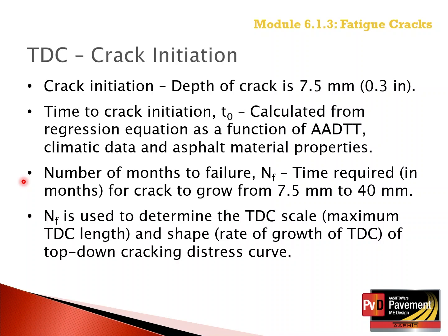The number of months to failure is then used to determine the top-down cracking scale for determining the maximum top-down cracking length and/or depth, and the shape or the rate of growth of top-down cracking over time. In other words, the top-down cracking distress curve.